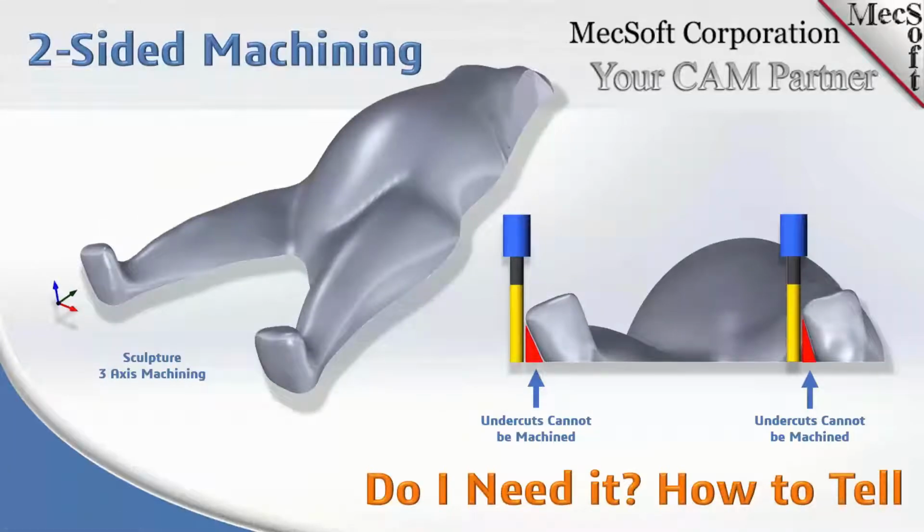So how can you tell if you need two-sided machining? Well, during your initial analysis of the part itself before you start programming it, obviously you're going to sit down, look at the part, and determine how it's going to be machined, how it's going to be oriented on the machine, and those kinds of things. So basically, if you see an undercut, as shown on the screen in red, then you can't machine all of it in one setup. Obviously, the tool is not going to bend down there and cut that out.